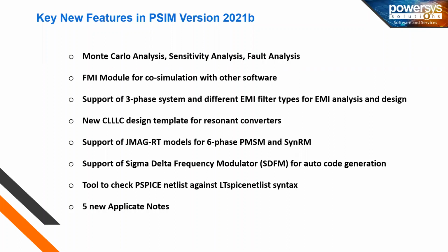We have added the capability to check the netlist when you want to import a PSPICE model into PSIM. You need to check if the netlist is compatible with LTSPICE, because only LTSPICE is compatible with PSIM. So now you can directly check and compare the PSPICE model netlist against the LTSPICE netlist and check if the netlist is well transcribed. You can then use LTSPICE directly. It will work. It will give you the compatibility or not between the PSPICE and LTSPICE engine, depending on your netlist.